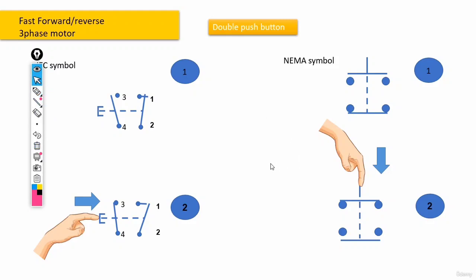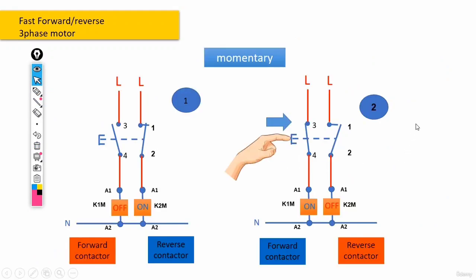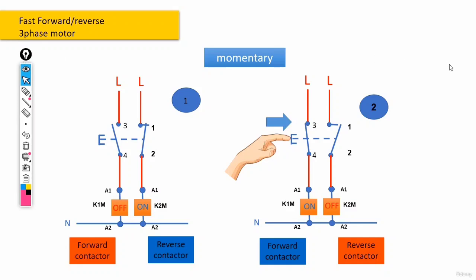Now guys, another question, what is the exact usage of this equipment? If you remember at the beginning of this very session, we said that we want the conversion in the motor to happen faster. And this is where exactly we can use this button. More specifically, guys, before we would have used two separate contactors, one for forward, the other one for reverse. But now, we've actually done something else here.